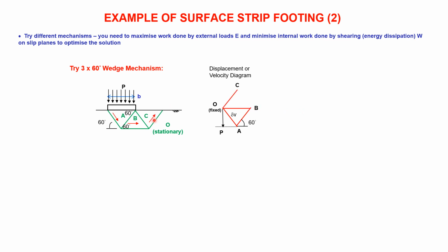Then we know that C, relative to the stationary soil, must be going up in this direction. So relative to stationary soil O, draw a line up that way at 60 degrees. Again, you don't really know how far to go, but you do know that B relative to C is that line there, so it must be coming in here somewhere, and they must join. So there it is. B relative to C, well, B would be going down that way relative to C going up that way on this failure plane, and you transfer that angle onto here and almost join.